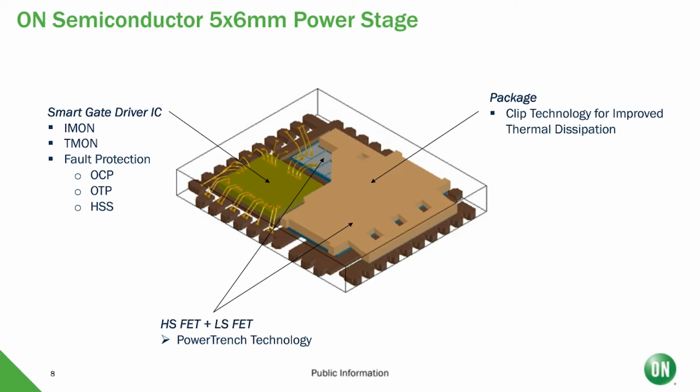So the controller knows the highest temperature of the power stage, and is able to perform an over temperature protection mechanism, so that we don't allow any of the phases to exceed a predefined threshold on the temperature. For example, like 100 degrees C or 120 degrees C.